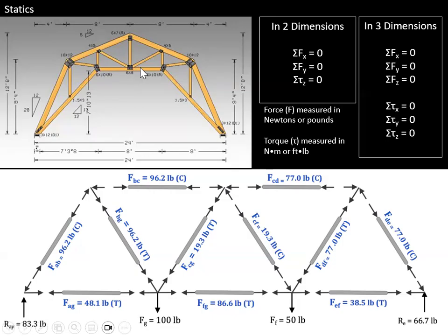So if you're putting in big rods where you only need a little tiny rod, that's just unnecessary expense. One way to think of engineering these structures is you want to make it equally strong or equally weak throughout the entire structure. You don't want one part to be really strong and one part really weak, because that would not be effective.